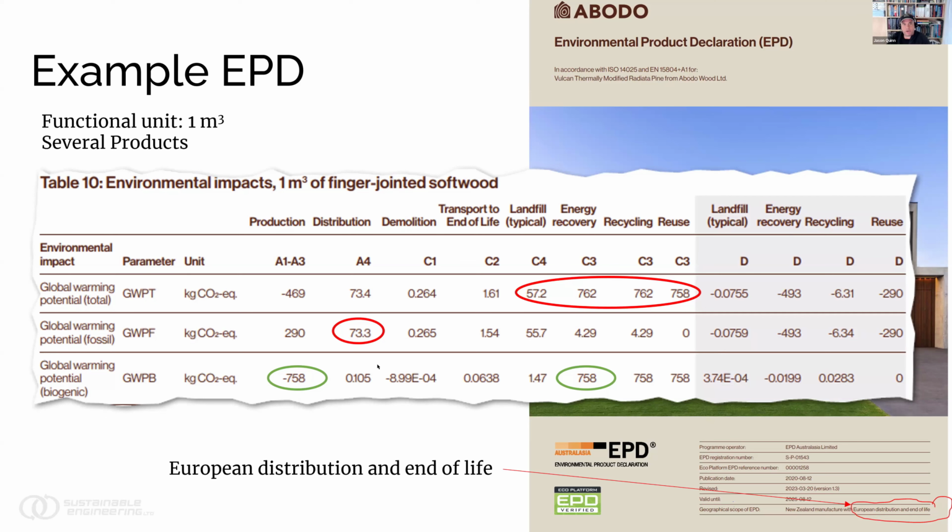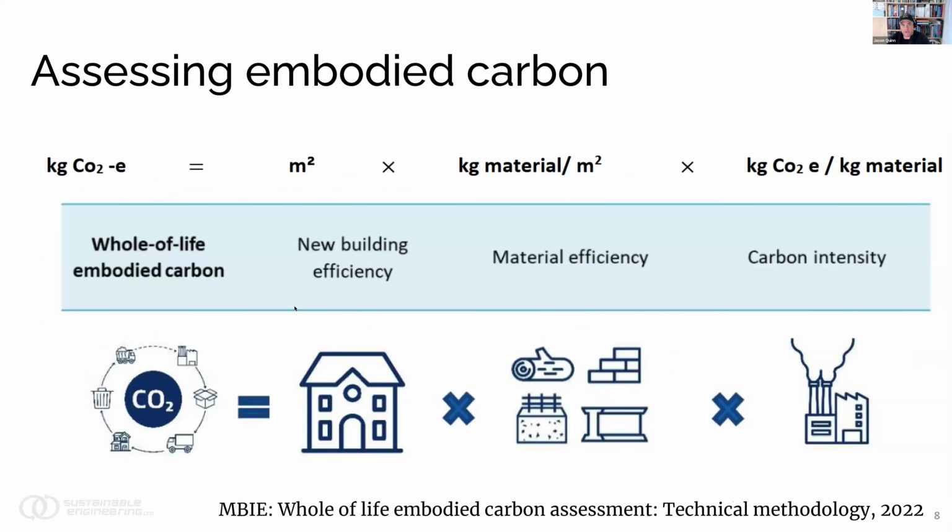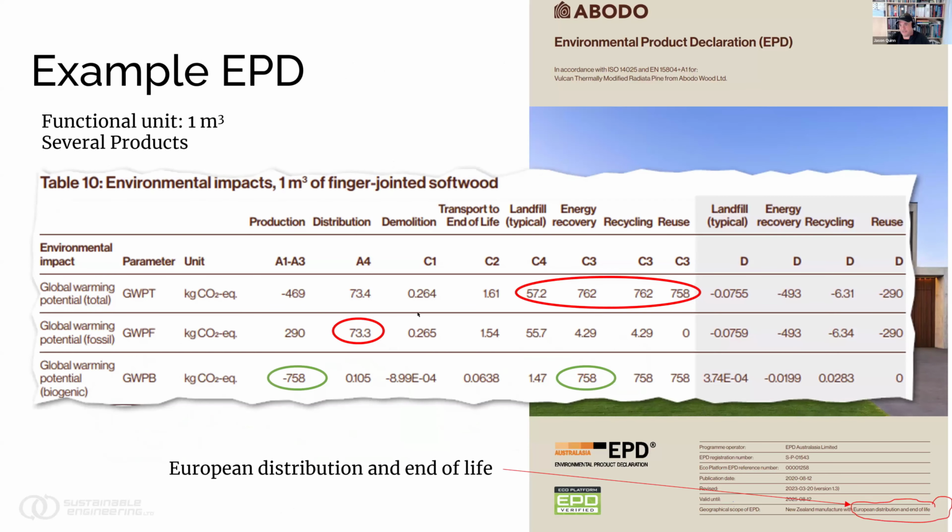So the embodied carbon is relatively straightforward. All you're doing is using the tool that has the building geometry in it to do energy modeling, multiplying by a badness factor of that material to get the emissions in the different phases. So it's basically a giant sum if statement in Excel, right? It just takes a column of how much area you've got times how much stuff you got in each layer, times its badness factor to get the carbon, right? And it's broken down in these phases. So if you have maintenance requirements, it keeps track of those maintenance requirements in that Excel table. So it's just an accountant exercise.